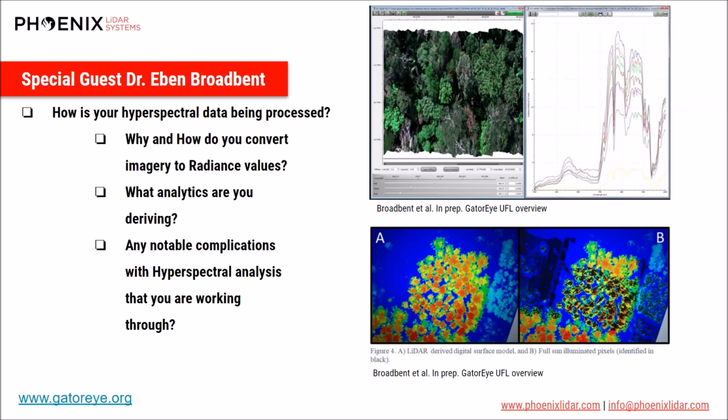So what I just talked about was pre-processing within the forest itself, getting rid of that shade by sending the light down. However, there's another key component here, and that's the fact that the intensity of the sun itself is constantly varying because there's clouds and different types of atmospheric components, and different sun angles, etc. So it's key that you convert your radiance into reflectance. Otherwise, once again, you don't have data that you can use for much.